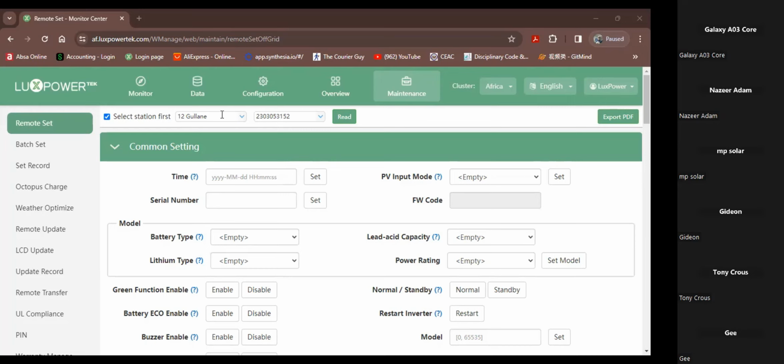When you are speccing or designing your system, if you're stringing your panels, look at the design of the panels. Don't exceed the short circuit current or the rated current of 13 amps or 15 amps. Don't exceed the 380 volts in your string. And obviously with the 3.3 kilowatts as well. You mentioned in your question about bridging your strings.